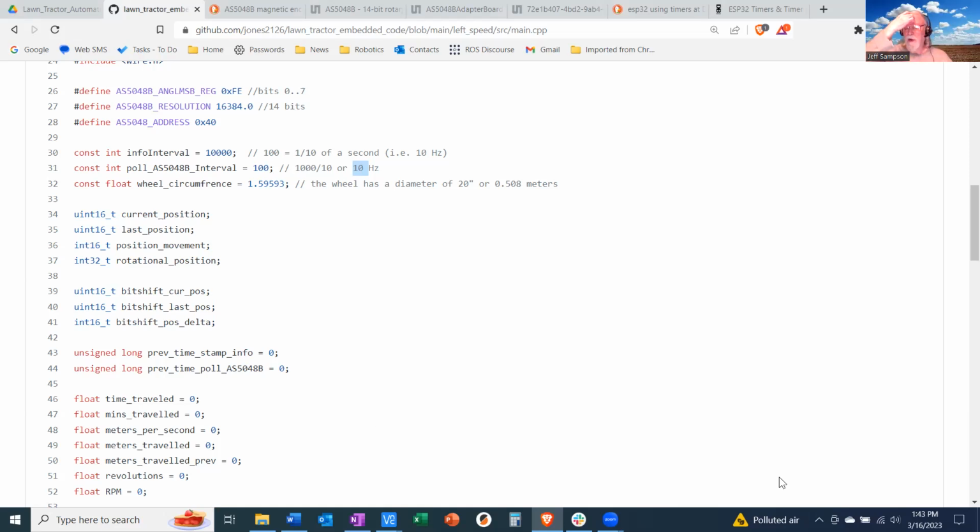And another interesting point, you could look at that chip and say, is an analog output always enabled? And can you run your I2C interface and the analog at the same time? So you could then take the analog and run it through an A to D. That's going to give you a number representing, see if that number scales to the value from the I2C that you're getting. And I don't know if that would be worth doing all the time to verify the things are working. I think as far as the chip's concerned, those two numbers will be equated together all the time. So I don't think you're going to detect an error based on that, but that'd be interesting to know.